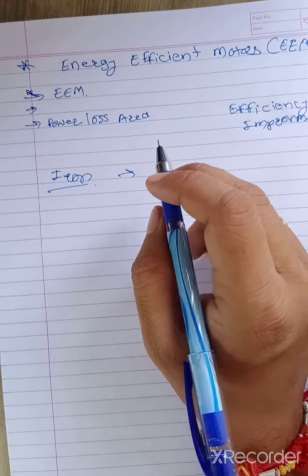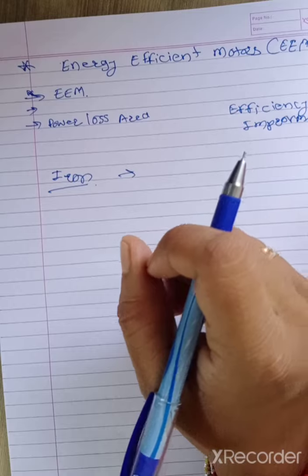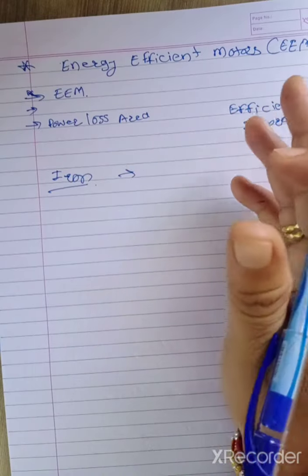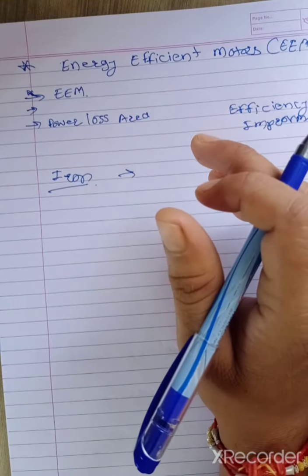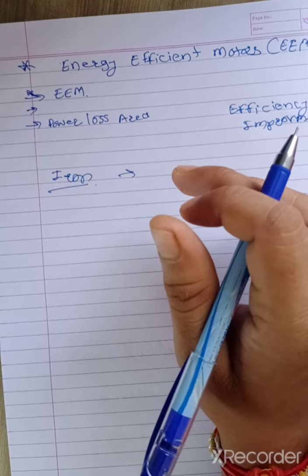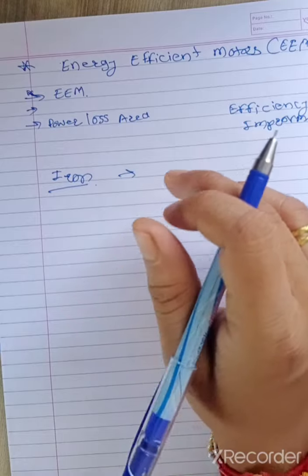Use of thinner gauge, lower loss core steel reduces eddy current losses. Longer core adds more steel to the design, which reduces losses due to lower operating flux densities, etc.